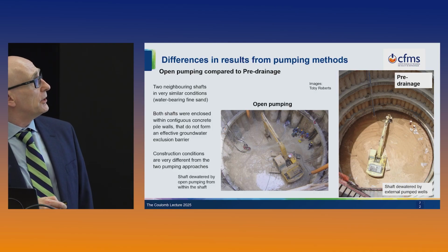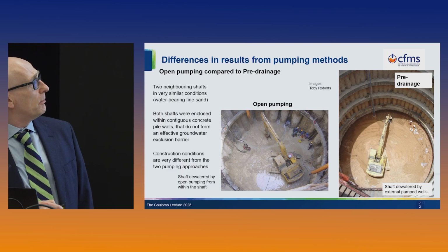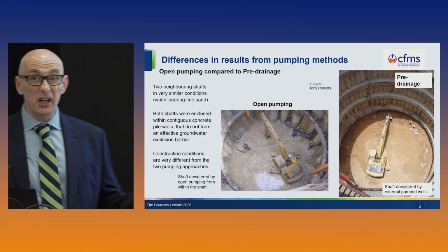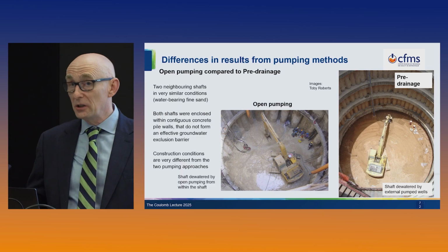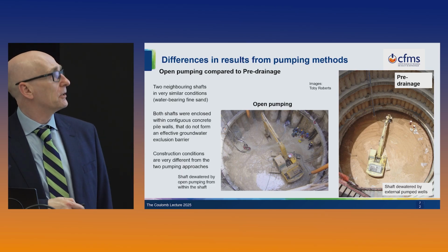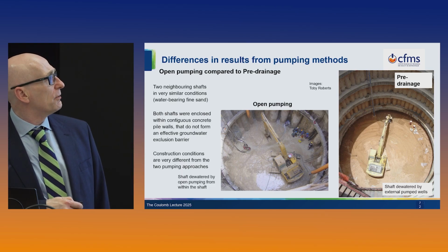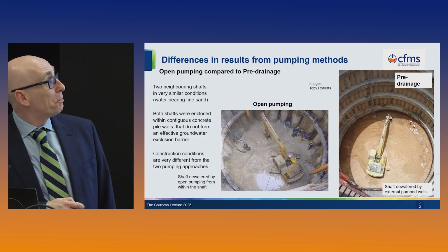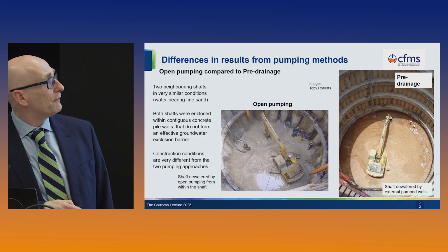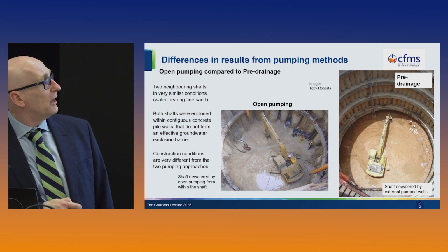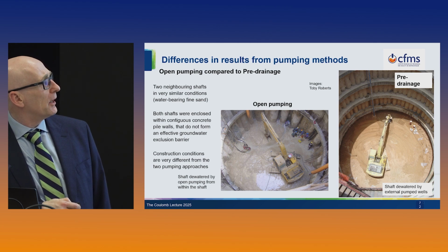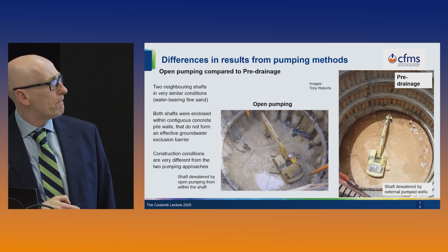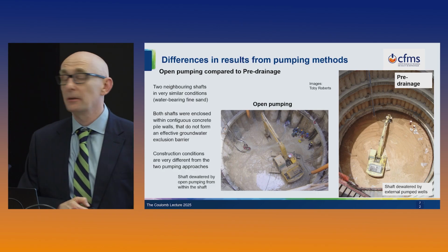And you can look down and you can see the pile wall, there's a sump pump there, and you can see that in theory, this is dewatered, it's not flooded, the excavator hasn't completely sunk in, but you can see that the water around the pump is dirty, so that's going to be a problem when it's disposed of. The operatives here don't look like they're having a lot of fun from this. Water's flowing in between the piles, there's lots of slurry and mess. It doesn't look very efficient, does it?